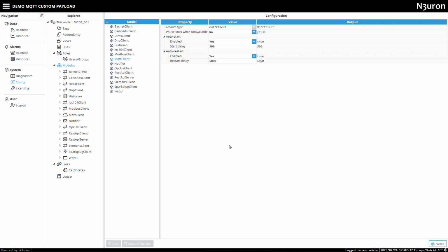Hello everyone. In this video, we'll show you how to configure a custom payload for the N3uron MQTT Client module. While the MQTT Client publisher comes with pre-configured serialization formats for JSON, InfluxDB, and protobuf, we'll demonstrate how to create a custom serialization for your custom payload using the broker configuration connection we established in the MQTT Client configuration video.